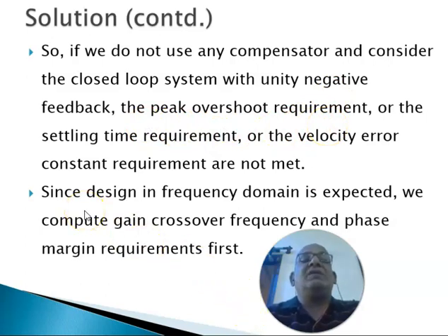So, design in the frequency domain of a compensator is necessary. Since it is necessary, we'll try to convert the time domain specifications into frequency domain specifications. That is, we'll try to compute the gain crossover frequency and the phase margin. We do that in the next slide.